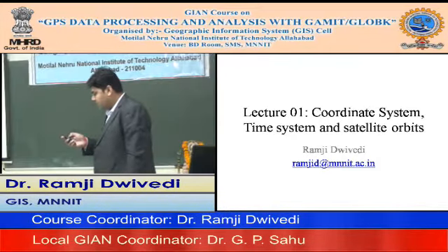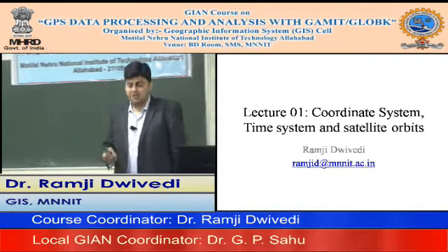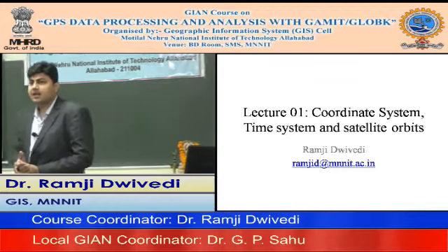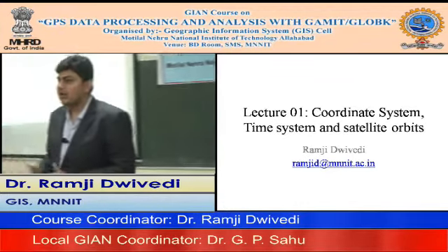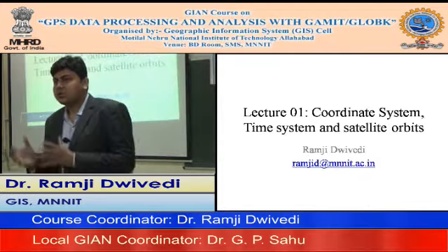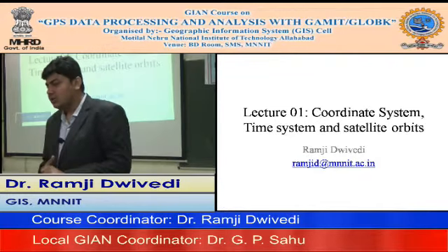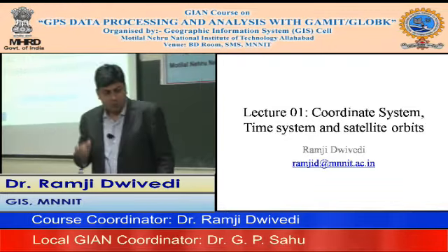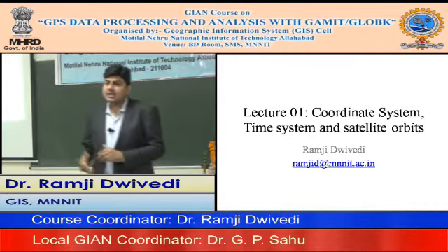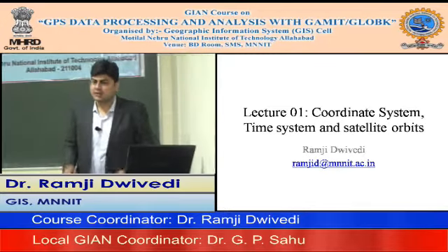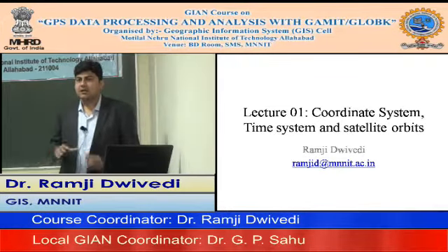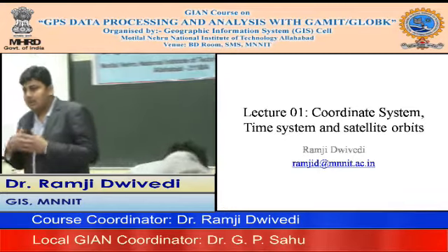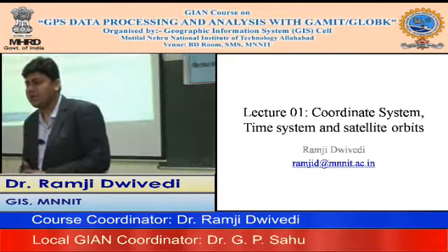The GPS concept takes this understanding that the satellites send certain signals, and those signals are modulated on a carrier. So we use the carrier as well as the code information which is available. But before this, since the satellite needs to connect to the receiver in a way that the position of the receiver can be computed, you need the satellite position.